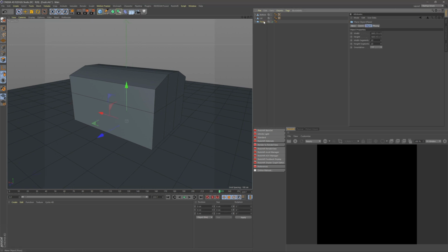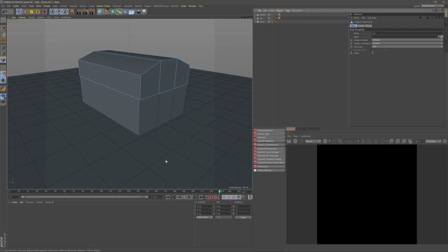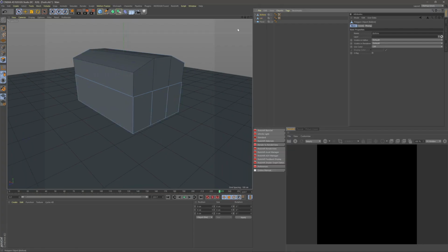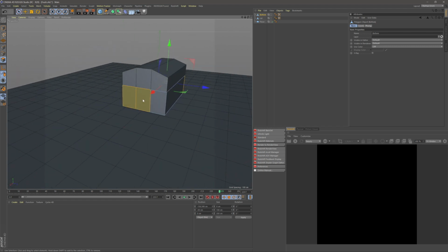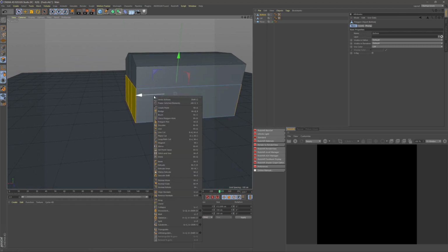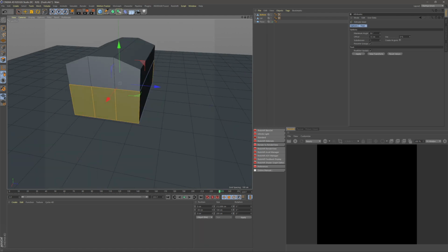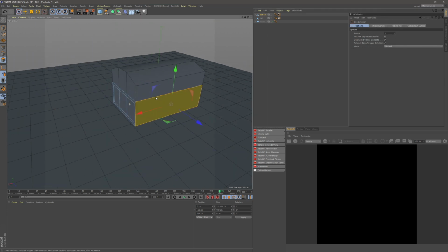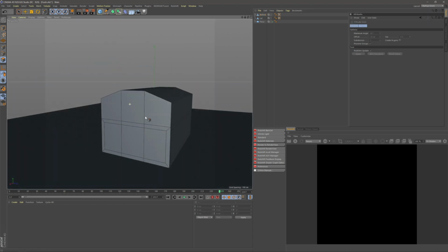Name our floor quickly. Cool. So adding these metal rims on this is quite simple. I'm just going to go ahead and grab my end polygons, right click and say extrude inner, and I'm going to extrude it in by say 10 centimeters, and I'm going to go ahead and do the same with the front and back ones. Right click, extrude inner, 10 centimeters.